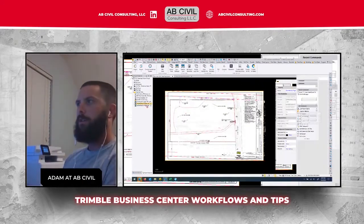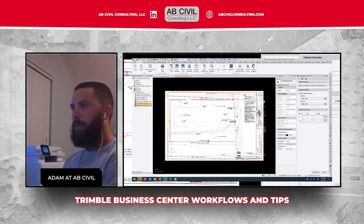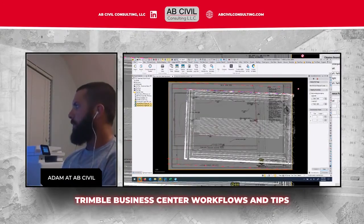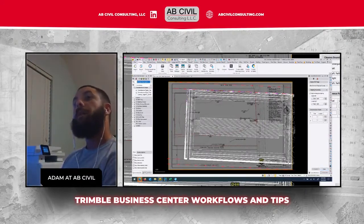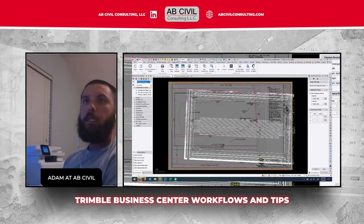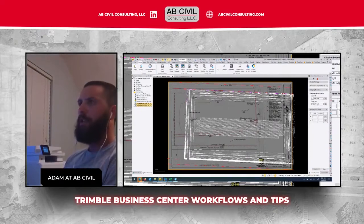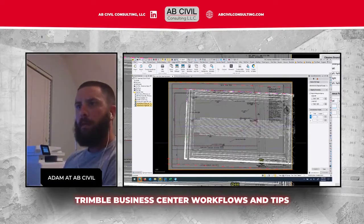Alright, so first thing I always do is highlight both my pages, and then I'm going to change that display style to dimmed. I did download TBC version 5.31, so some of my stuff got reset. Common complaint. So I'm not going to apply a clipping boundary to this because there's really no need. There's only one view. So I'm just going to start by picking a pixel here.